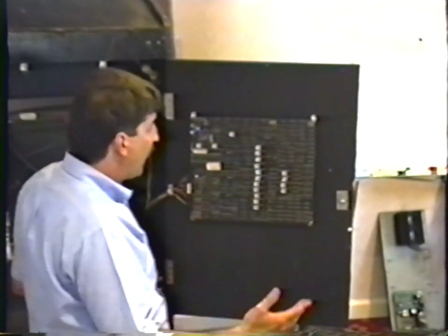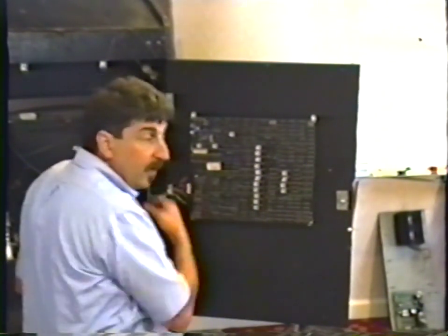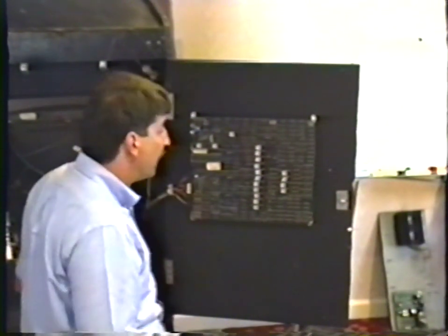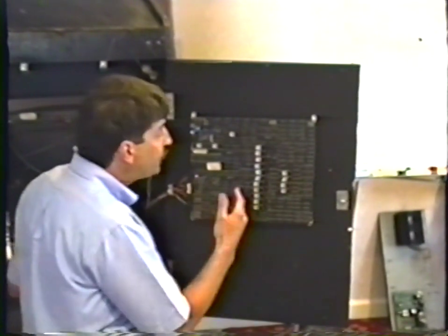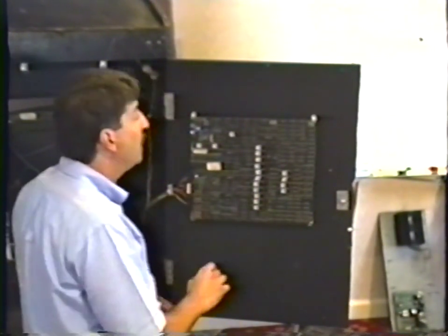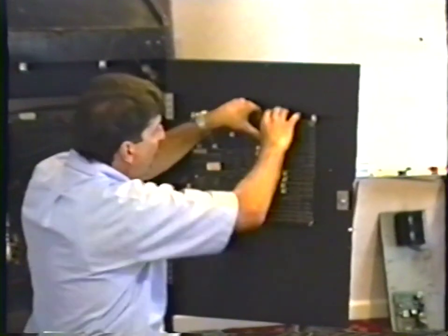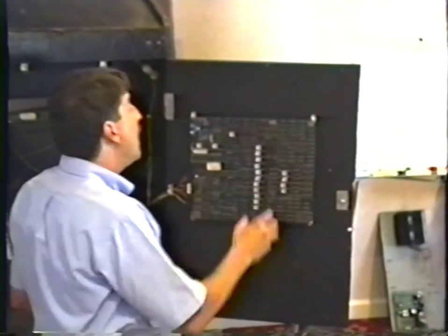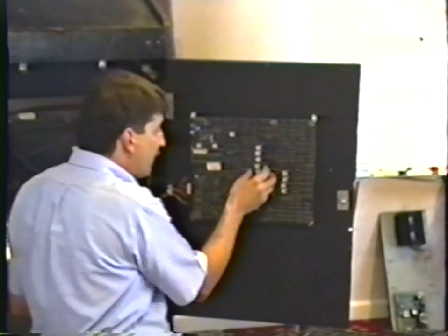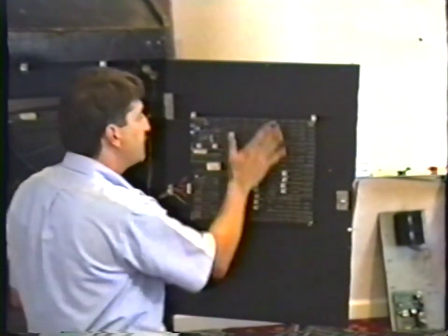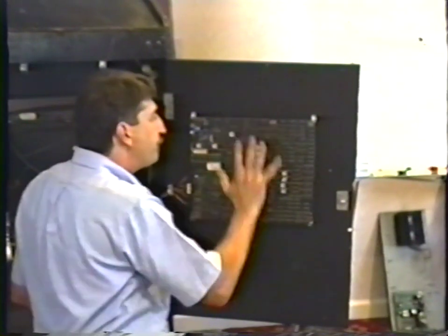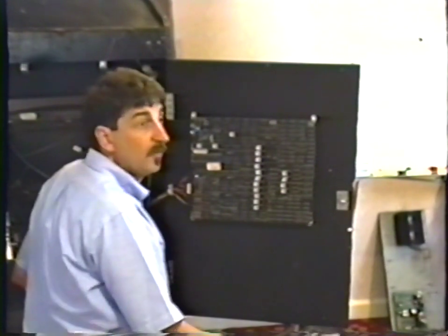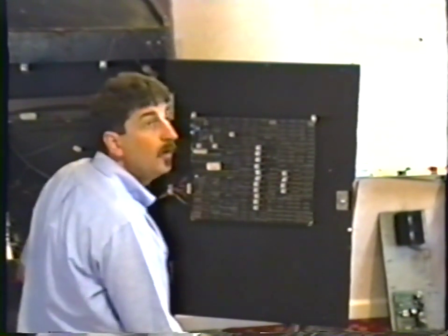So again, you get to the game, it's got this weird junk on the screen. First you check the power supply, because that's the most likely cause of that problem. But if all the power is okay, you definitely have a board failure. Don't give up. First thing, turn the power off, push on all the chips. Turn the power back on. Does it work? No. Carefully pull each chip out one at a time that's in a socket. Clean off the pins as necessary. Put them back in, fire it back up, see what you have. That really solves a lot of problems. I never send a board away without doing that first.